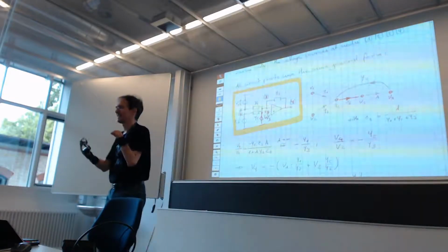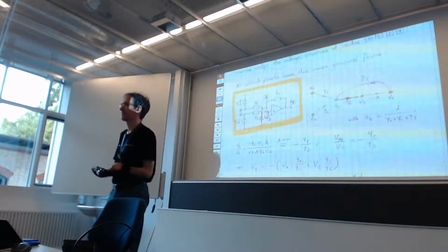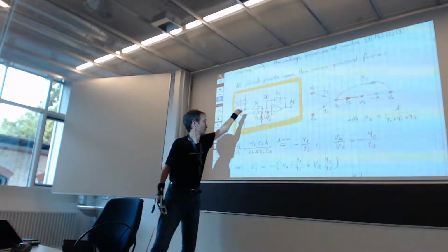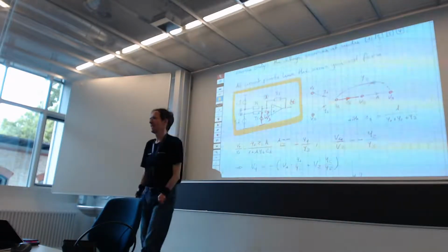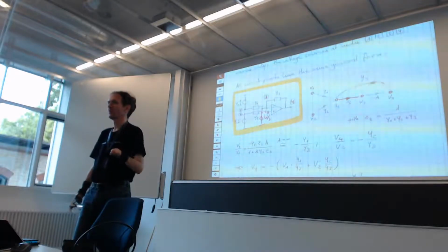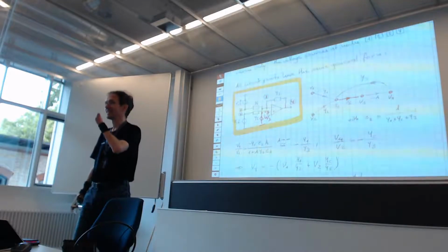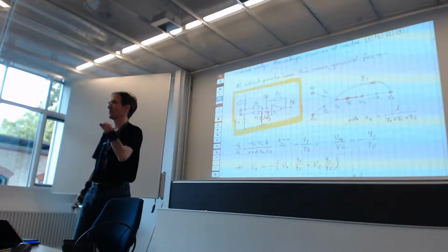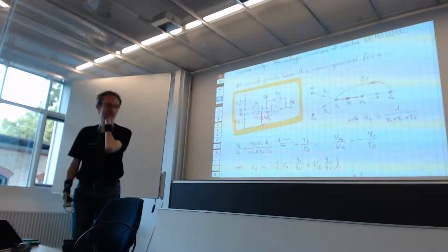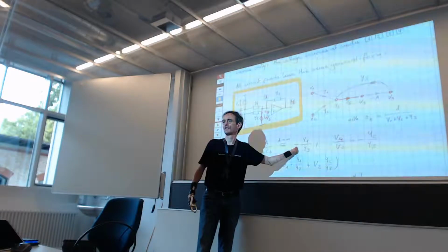So I have exactly the same as before. If Y3 is a capacitor, I have 1 over SC. And if Y1 and Y2 are just resistors, I have their conductance there just as I had the GM1, GM2, GM3, GM4 before. So this is exactly the same way I can do signal flow graphs if I want. With one exception, I do not have control over the sign. This is always negative.